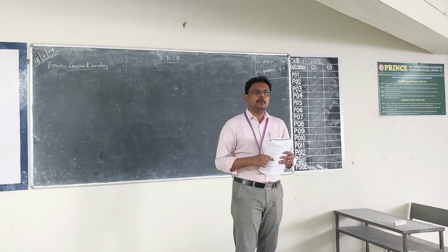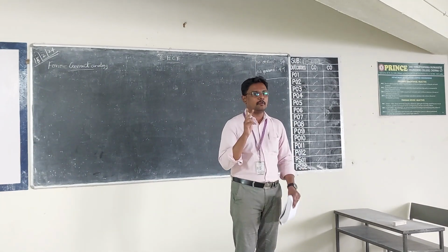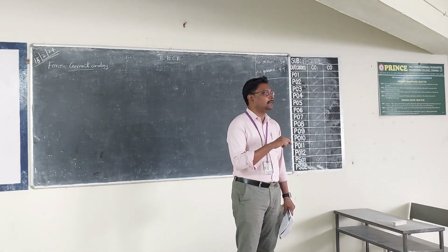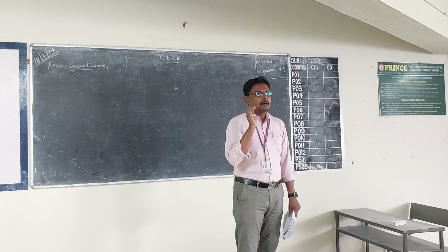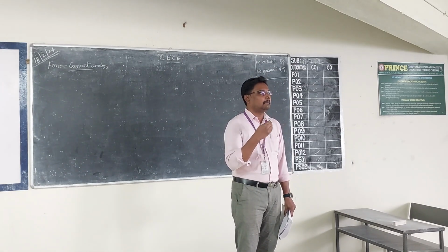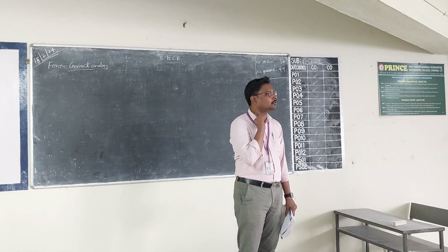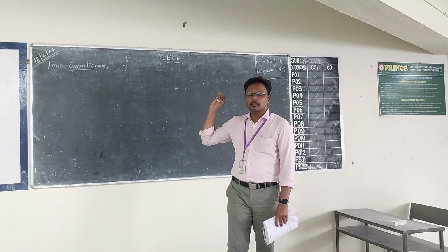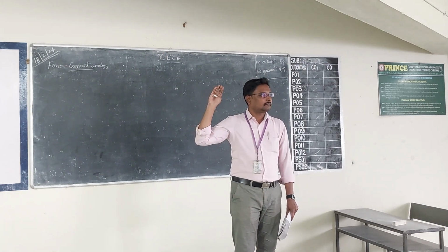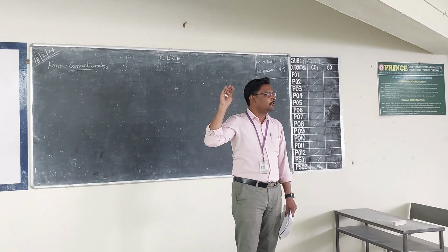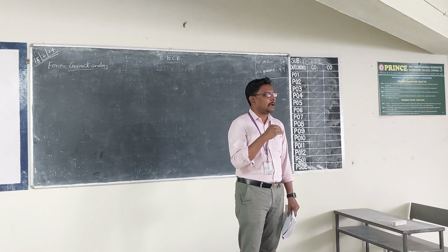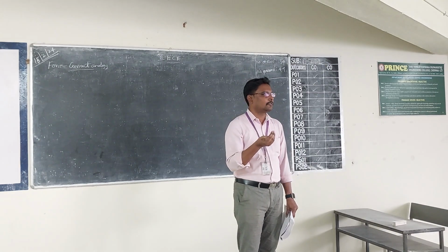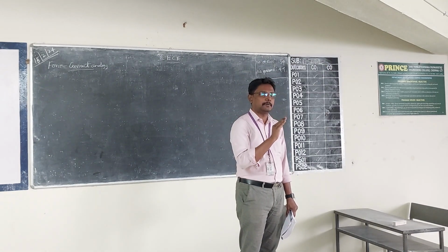See, totally how many nodes will be there? 2 nodes will be there. You are having 2 masses. The mass on which the applied force is acting will have the current source. Correct? Always the applied force to the corresponding mass will be taken as the source, whether it is voltage source or current source. Now we are going to see force current analogy. Here the applied force is given to the first mass M1, so you have to draw the current source in the first loop or the first node.